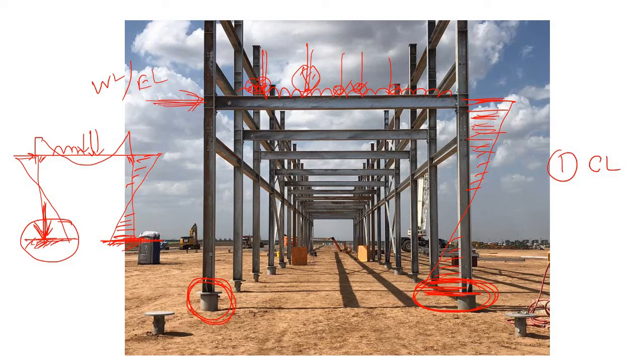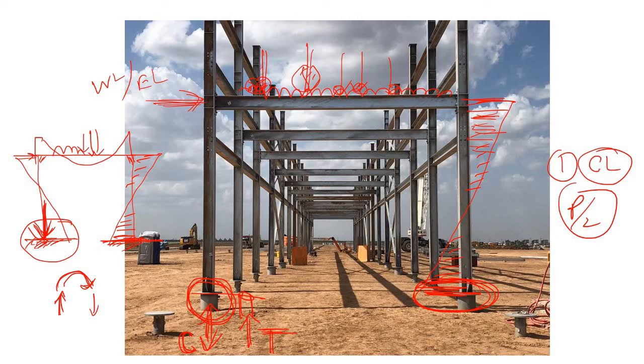And normally a bending moment is nothing but a push and a pull. So in that case, instead of providing a single pile, if you provide two piles, one pile will take the tensile force and another pile will take the compressive force due to this bending moment itself, and this vertical compressive load will be divided equally among these two piles.